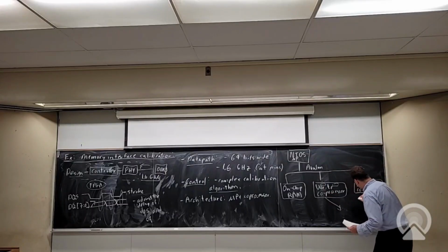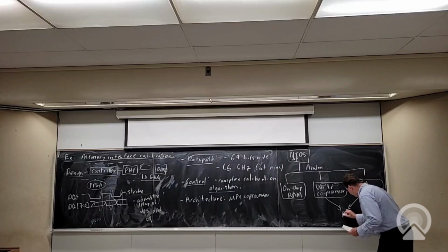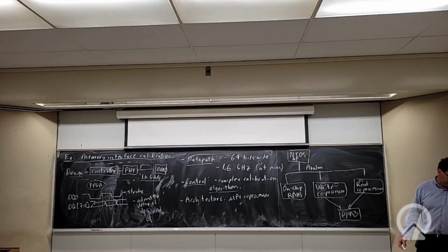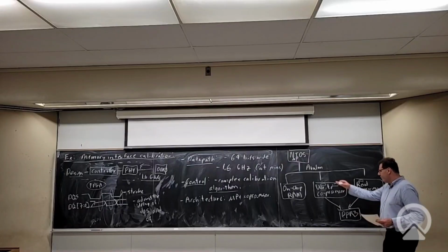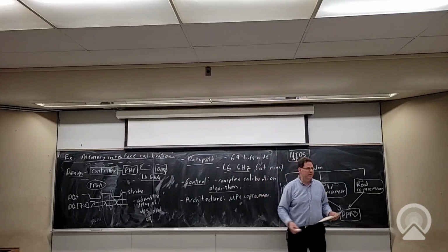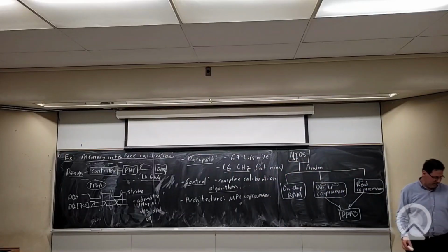So the processor is just reading and writing these registers over the bus. And these coprocessors can do anything they want, so they actually hook straight to the DDR. They hook straight to the device I/O pins and to the DDR3 chip. And they're fast, right? They can run at the full speed, 64-bit wide, 1.6 gigahertz.